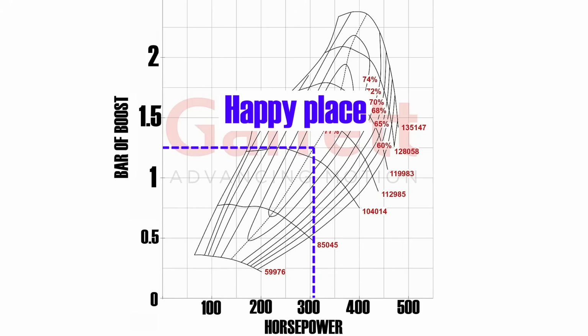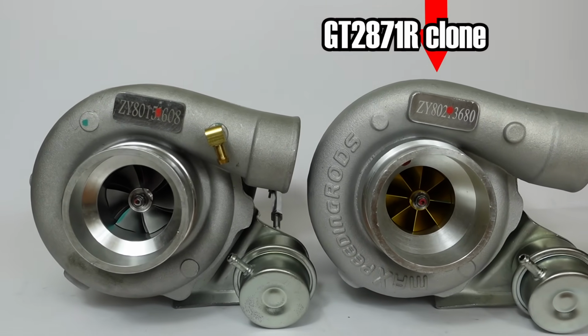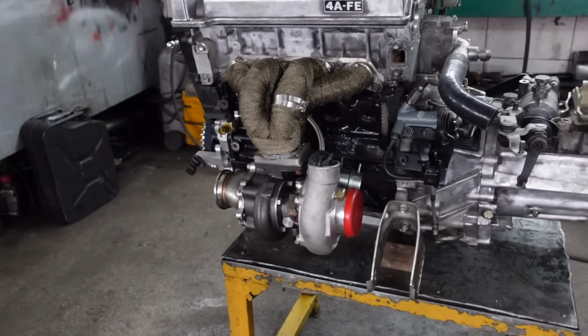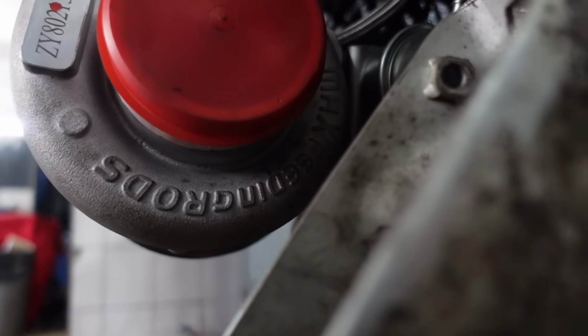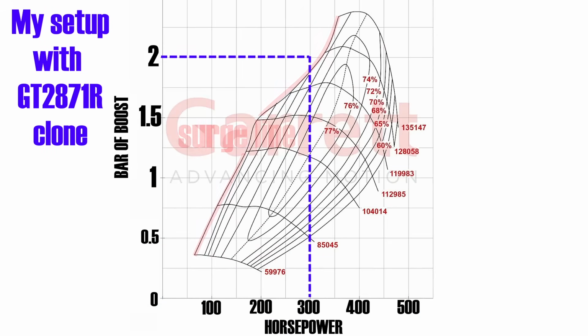Now, I'm actually running a clone of this very turbo on my project car, which is a 1987 Toyota MR2 with a 1.6-liter 4AFE Toyota engine, making around 300 horsepower. Of course, to make 300 horsepower from such a small displacement, I had to run 2 bar of boost pressure. If we plot this on our compressor map, you can see that I'm actually behind the surge line, which means that I should be experiencing surge. But in practice, there is no surge at all on my setup.